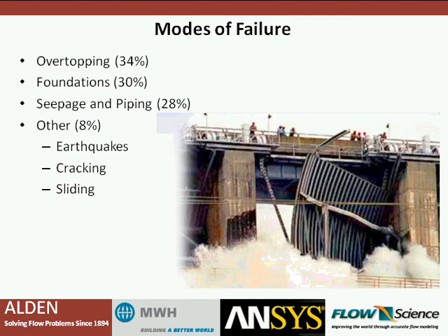Now that we know that dams fail, we might ask, well, how do they fail? The predominant mode of failure for dams is overtopping, and this is why the spillway issues that we're talking about today are so important. Overtopping can occur for a number of reasons. One, of course, is the spillway capacity just may not be large enough. And that could be due to a couple of reasons. There's been a series of changes in the way we calculate design floods recently, which has caused floods to actually increase from what the projects were originally designed for, and I'll get into that in a moment.